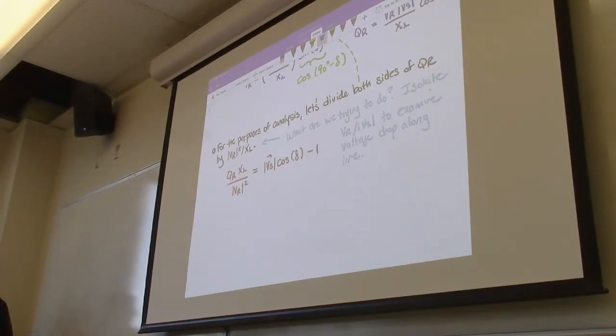This is an important part of the way that this system works. A lot like how when we were dealing with machines, we were talking about the stability region in terms of how far our internal angle of the generator was getting away from the terminal angle. In this case, we're going to be worried a lot when it comes to instability about the voltage magnitude drop from one end of the line to the other.